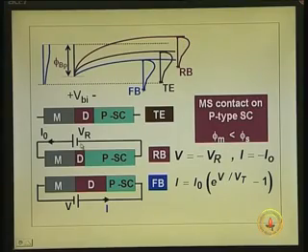So, now here this polarity of this voltage, if it is the same thing, the band bending there will increase, it will push the energy band diagram valence band upward. So, that is the reverse bias situation, that is whatever built-in potential was there, you add up this quantity, that is extra voltage that you are adding up, okay. That extra voltage added up is Vr and you get reverse bias.